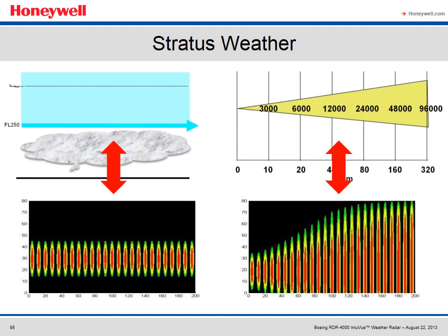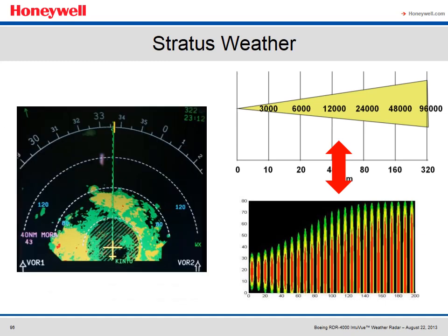This causes an apparent increase in the height of the cells, or in this case, the stratus layer. This can appear on the display as a halo or ring of secondary weather returns fixed around the aircraft. In this picture, the ring extends out to approximately 37 nautical miles. At longer ranges, the weather is showing up as flight path weather because the decreased resolution causes the stratus weather to encroach into our 25,000 foot boundary. But as the weather gets closer and the resolution improves, it becomes secondary.